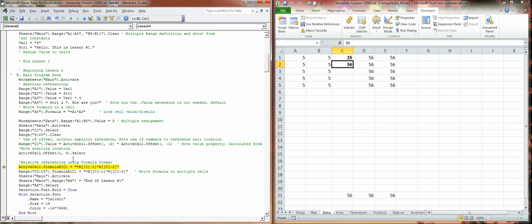All right, now we're going to execute and say we're going to select one row down. Hit the F8 key. You notice it moved one row down. In this case, now we're actually going to do a little bit more powerful operation, just like we talked about before. We're actually going to write a formula into a cell, and let's put that in there. Let's go and execute F8 again, and you can see what happened here. It put B2 times A2, and the value there is 25 again. Alright, so similarly, there's a nomenclature here that's very similar to what we did up here, where we say equal R braces. There's two braces there, which means we're staying on the same row.